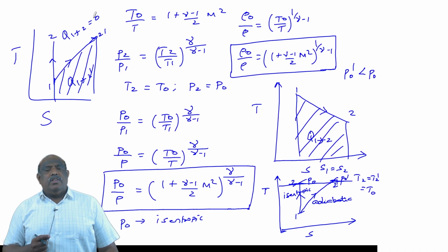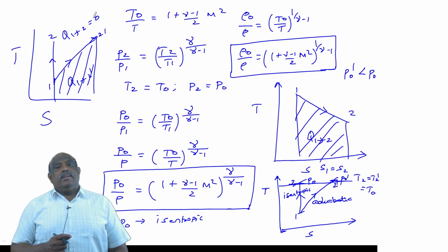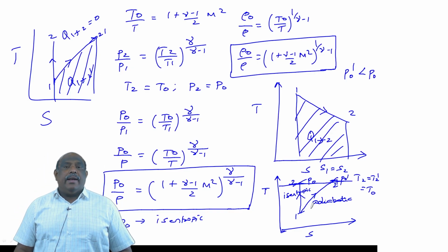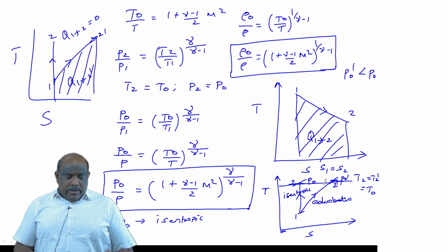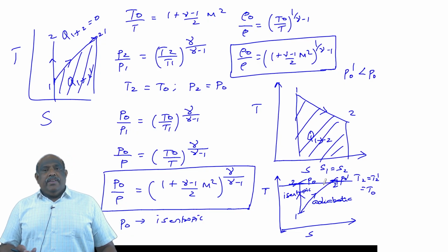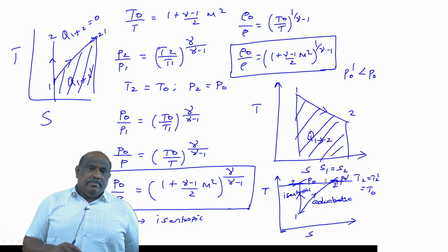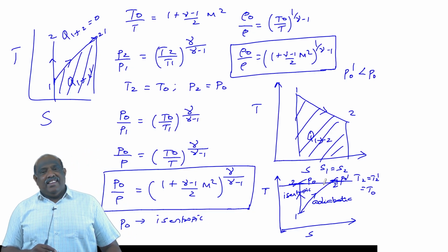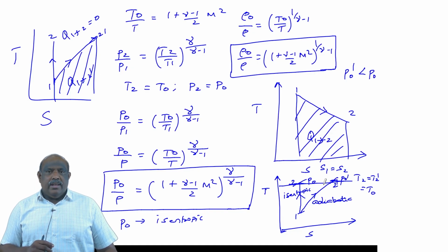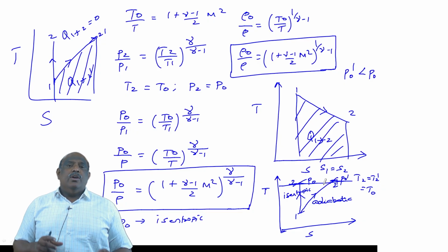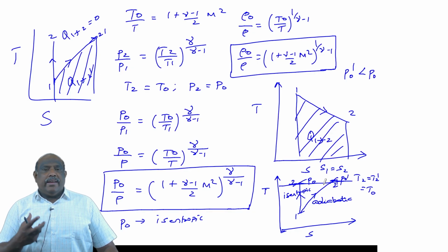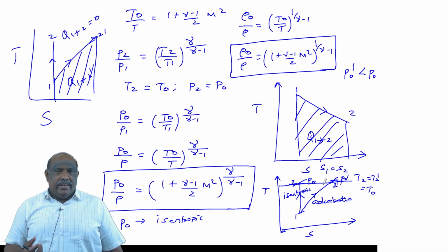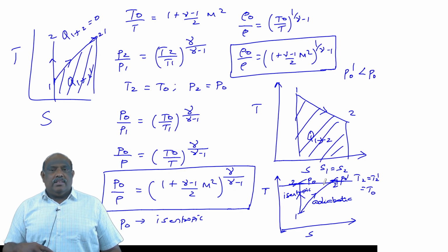So, my students will always ask me a question. Sir, you told it's already adiabatic. The process 1 to 2 dash is what? Adiabatic. Adiabatic means what? No heat transfer, which means there should not be any heat transfer from 1 to 2 dash. But here you are showing some area which doesn't reflect it to be adiabatic. Can anyone tell what the answer is? There should not definitely be an area under this 1 to 2 dash because adiabatic means there should be no heat transfer. But still there is some area under the graph 1 to 2 dash even though it's adiabatic. Then students, you please help me how I can prove that 1 to 2 dash graph is not wrong. Even though it's adiabatic, but still there is a heat transfer.